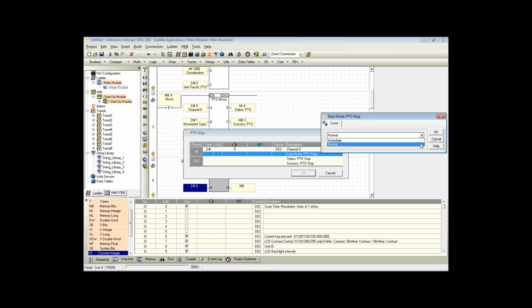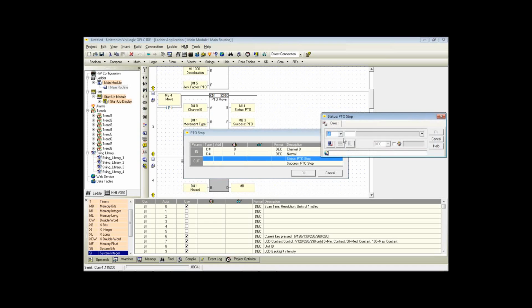Now, in stepper motors, immediate stop is not a real thing, because immediate stop cannot be performed with a stepper motor. Once you stop giving it entering pulses, it will continue to move. So this is a very delicate decision to make for the stop module.